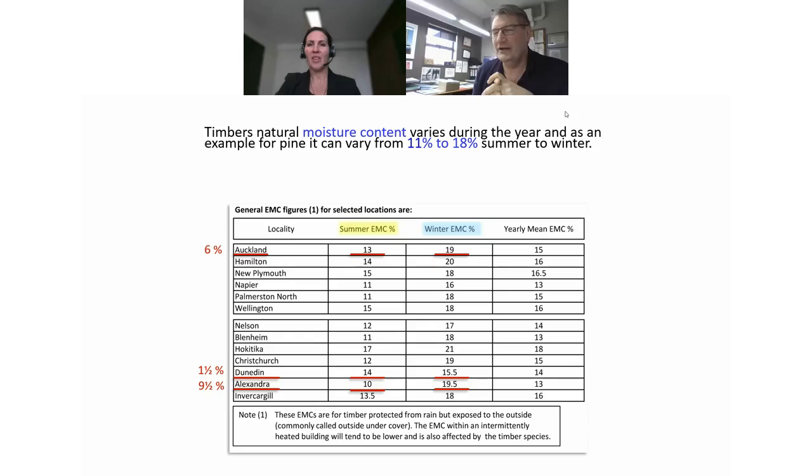And I'm not going to joke about Northland because they've had a really rough time lately. At the moment, they've had a lot of rain and it will be horrific up there. But I deal with environments all the time with the corrosion of metals, right? The closer you get to the equator, the more tropical it's going to get. And basically that means you're going to have a higher humidity, which is a higher moisture content, which is more moisture available to absorb. We're talking vapor, by the way, we're not talking liquid here, but vapor naturally absorbs into it. So Northland would just be very, very similar to Auckland, if not just a little bit worse.